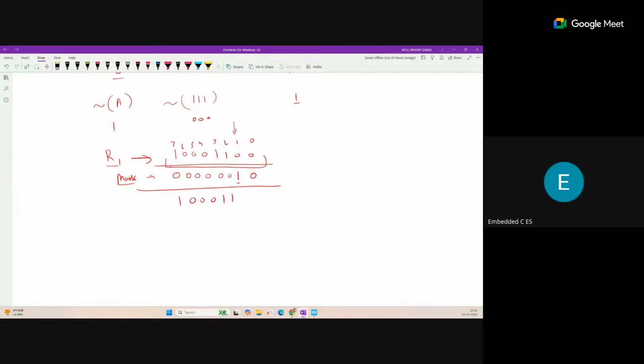So we are taking another binary value to perform the OR operation with the actual value of the register. Whichever bit we want to set, that is, make a 1, corresponding to that we will set a 1 in this other value, for the OR.